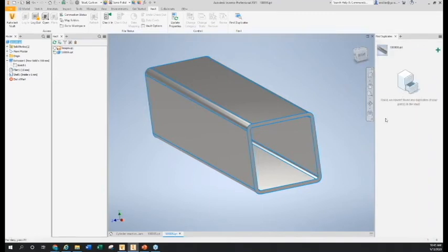This is what happens if it doesn't find anything. It said, good, we haven't found any duplicates. So I just increased the length there by 50 millimeters, and now it doesn't have anything that's similar to that. So it's got to be exact.